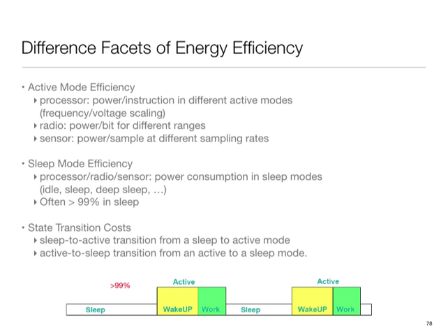Usually processors provide this capability that you can put them into sleep mode, and then in response to some sort of interrupt or a timer interrupt, they can come out of sleep mode. Radios provide similar things: network interfaces, you can put them into sleep mode, and then a packet of some special type can wake them up, or a timer can wake them up.